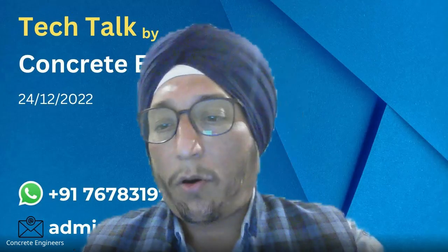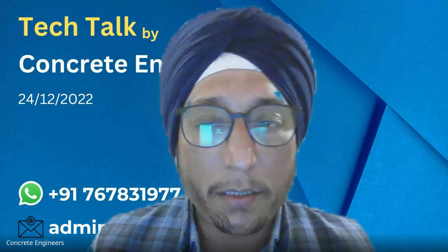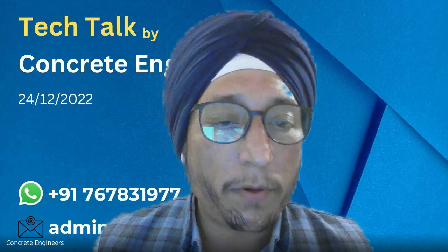Probably this is it. And one question from Siddharth ji also, sir. Siddharth Bhat asks: compatibility of blended cement PPC, PSC, composite cement with SNF, PC and SP. If projects where chloride is encountered along with sulfates in soil or groundwater, which admixture and cement is advisable? See, actually when chloride is there, definitely blended cement should be used, especially PSC, Portland slag cement.